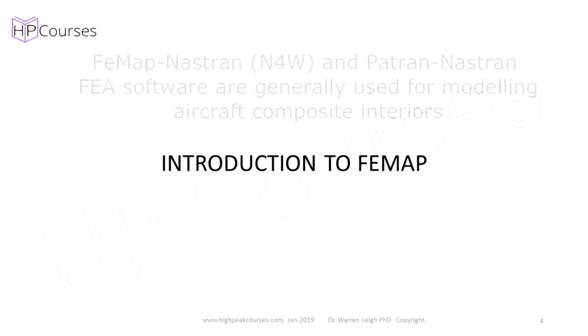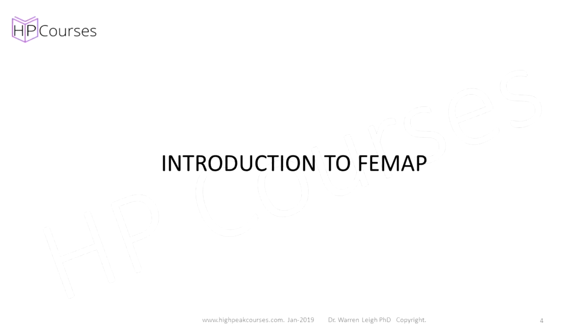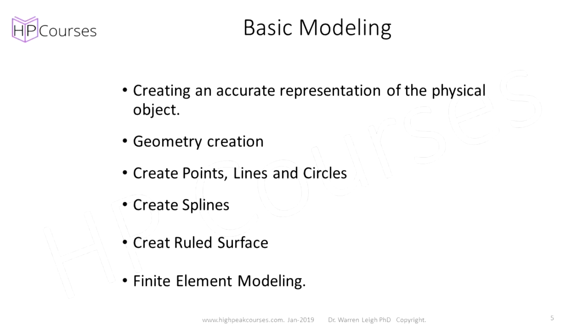In either Femap or Patran, we start by creating a new database. All this means is giving your project a name and saving it in the correct directory. Shown here is a simple exercise in Femap.